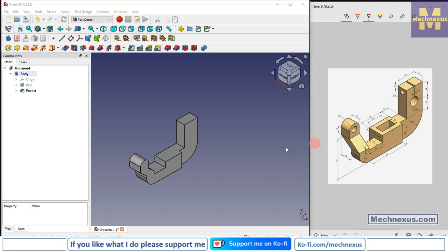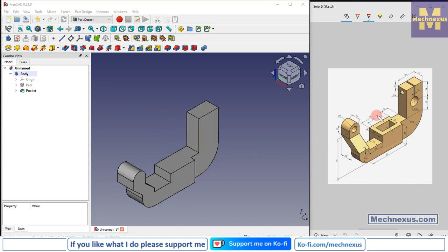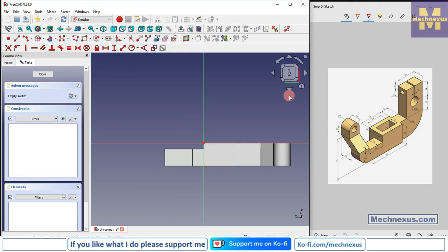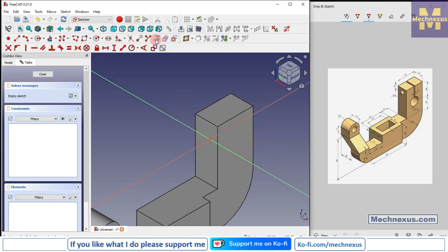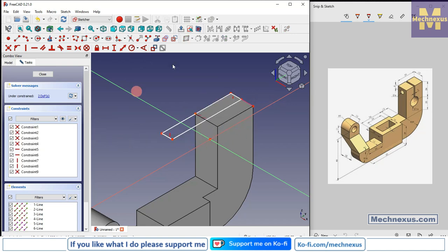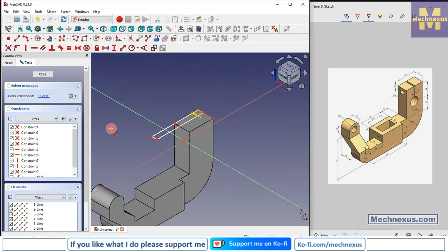Now we will do the same cut on the other side. So we will select this top face and click on the sketch, press 0 for isometric, click on project these two, and select rectangle and select smart dimension and give it 6 mm, and we will project this edge.